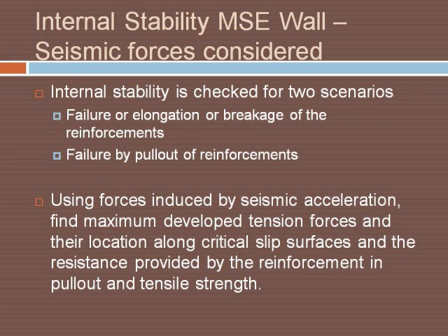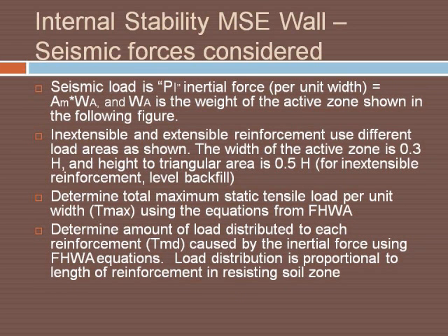pullout of the reinforcements. The internal stability of the MSE wall depends upon seismic forces and static forces in the reinforcement zones. Seismic load is basically the inertial force from the active zone pushing on the wall. The active zones for extensible and inextensible reinforcement are a little bit different, as seen in the following figures.